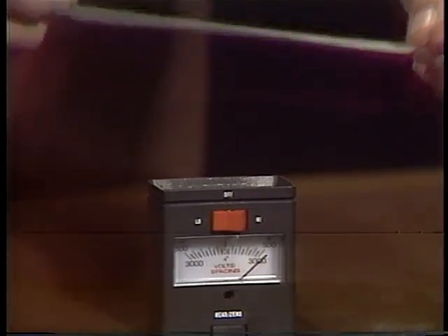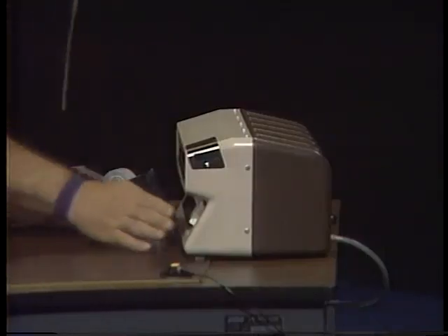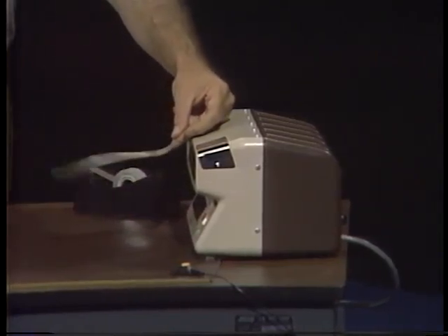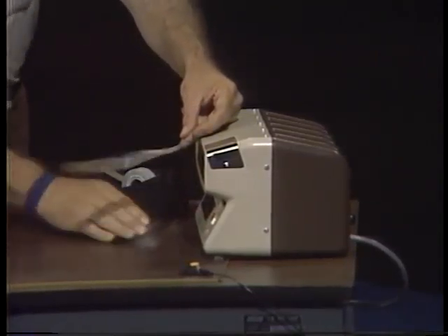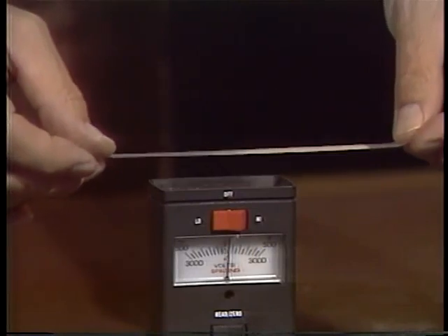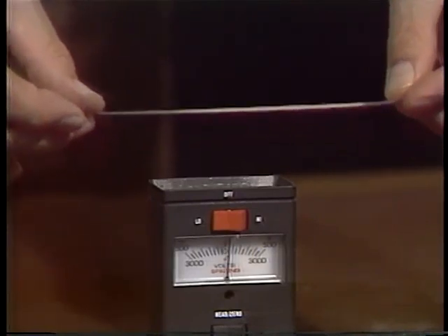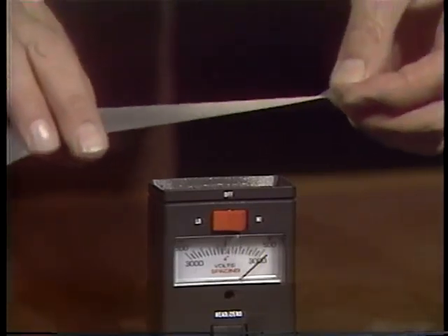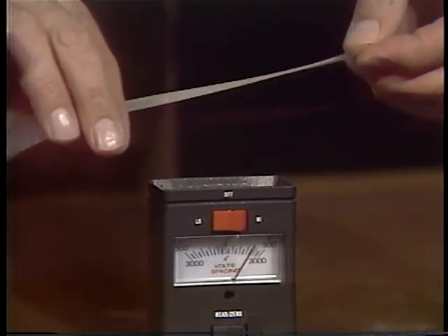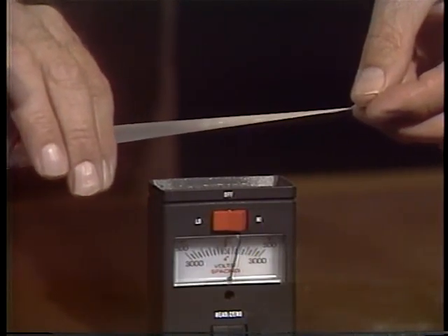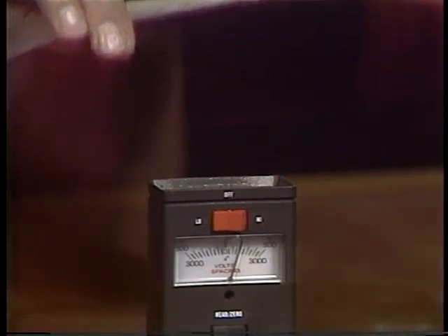However, if we turn on the ionizer and place the tape in the air path of the ionizer for even a few moments, now we find that the tape is no longer charged. It has not been made permanently anti-static because I can restore a charge to the tape merely by handling it. But the ionizer will reduce the charge as we sit here and watch.